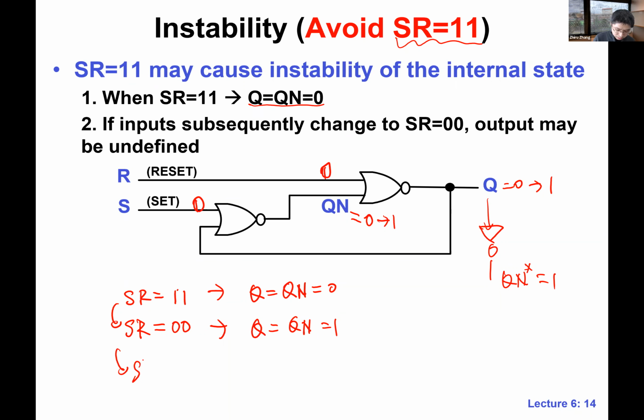And we can try to keep holding. This is something you guys should try to figure out. What is this? Okay. So actually we will come back to 0 again. And basically this thing breaks, so it's no longer holding. With our internal state, it's already messed up. When S and R are both ones, it's sort of messing up our internal state, and we can no longer hold. All right. I just want to help you guys understand why we want to avoid this.